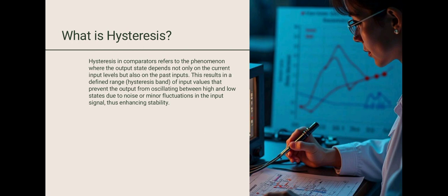What is hysteresis? Hysteresis in a comparator refers to the phenomenon where the output state depends not only on the current input levels but also on the past inputs. This results in a defined hysteresis band of input values that prevent the output from oscillating between high and low states due to noise or minor fluctuations in the input signals, thus enhancing stability.